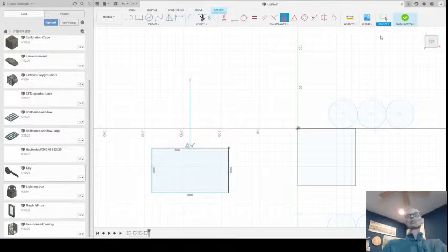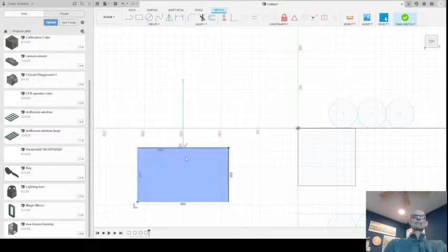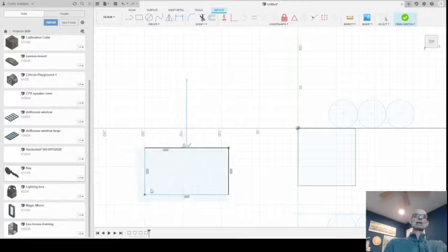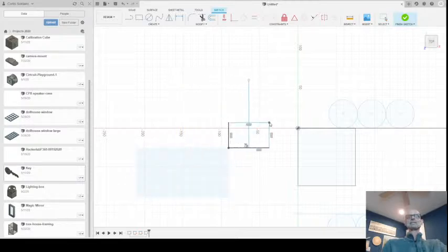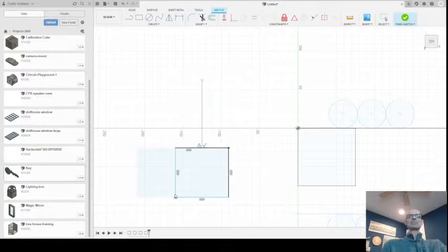But you'll notice that the lower left-hand portion of the object is not fully constrained, and I can demonstrate that by grabbing the lower left-hand corner and scaling and moving that all around. Now, this top line won't move. It'll scale because this side is not constrained. Only this point's constrained. And this is the same for this side as well. So it can scale around, but it has to retain those qualities of the constraints that have been placed upon them. Even if I invert it, it still is respecting the constraints. It's a little bit different than this, but it's still respecting the constraints.